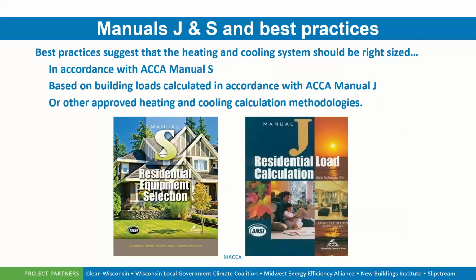Again, we've been talking about right sizing of equipment. So again, you're going to hit on this again, using that Manual J in conjunction with a Manual S. So we look at our calculation requirements, our airflows. Then we can design and select our equipment based on those requirements of the building as projected and be able to deliver a comfortable environment and an efficient environment for the occupants going forward.